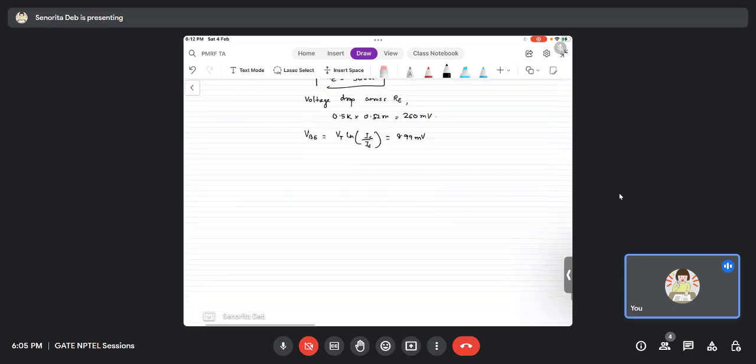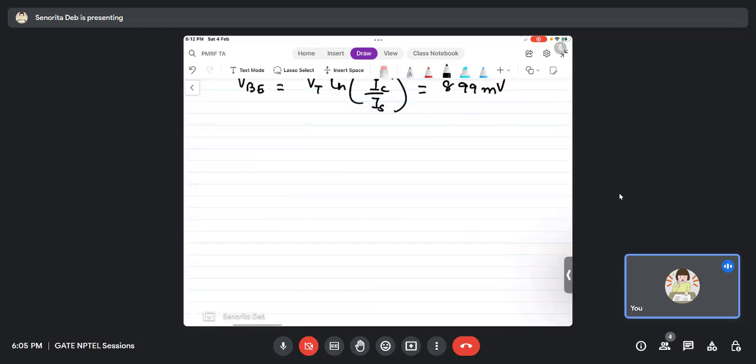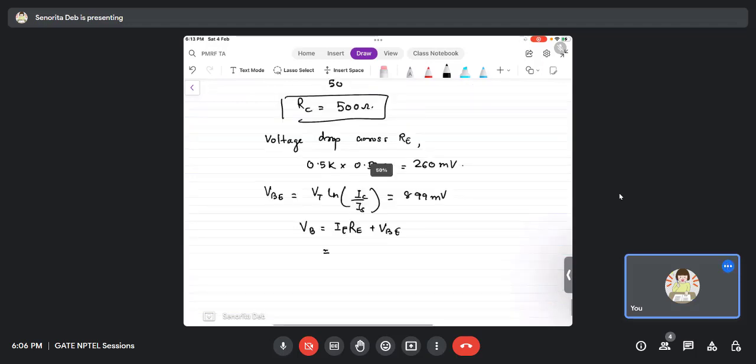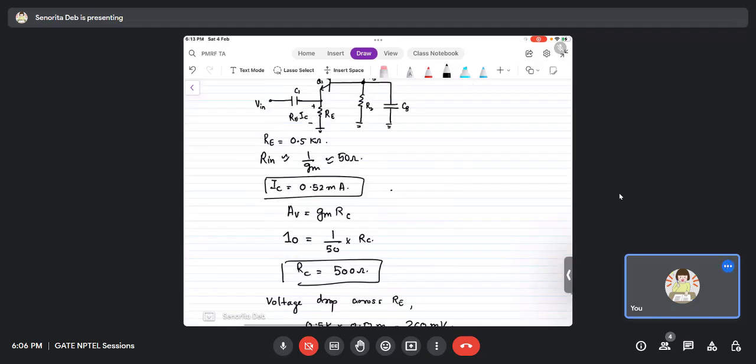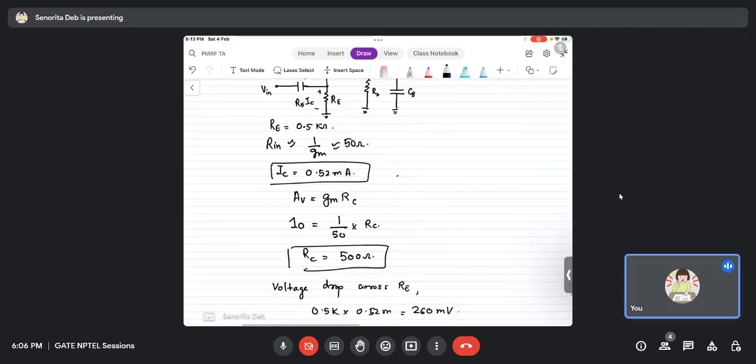Okay, so now till VE you have got. So if VE you have got, then VB you can find out because VBE you have. So VB is nothing but IERE plus VBE. So that was the reason to find out IERE first. So IERE we just saw, right? Here we have seen. So RE we have taken to 0.5 kilo ohm and IC we have got to 0.52. The same things we will put up and you will get 1.16 volts as VB.